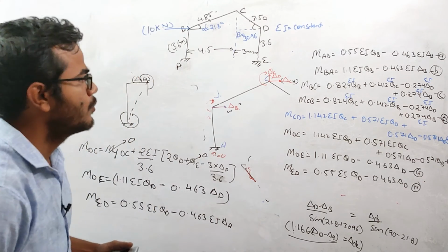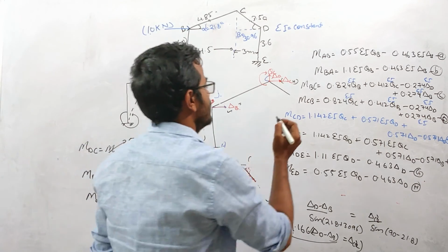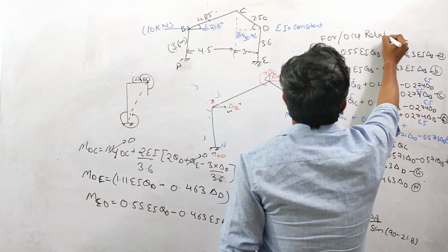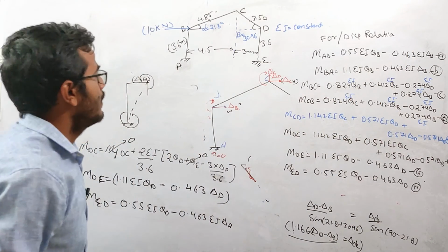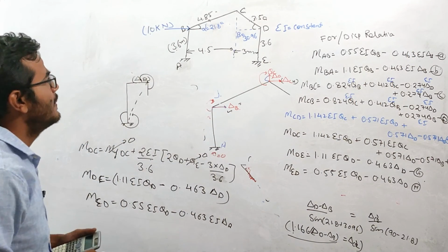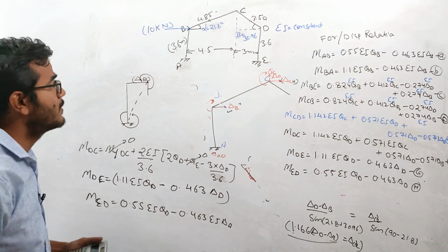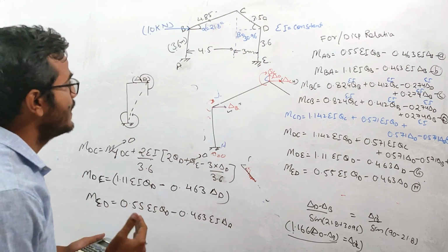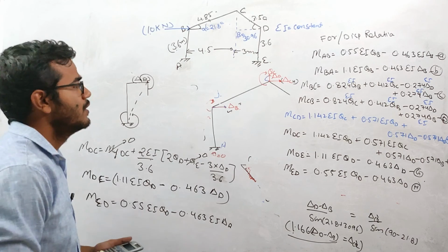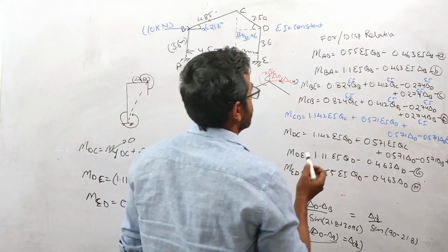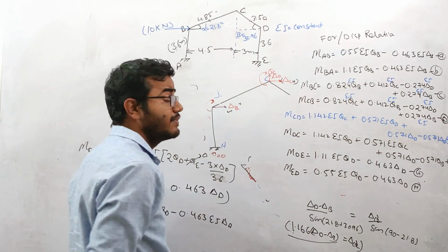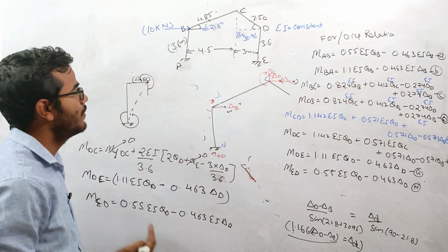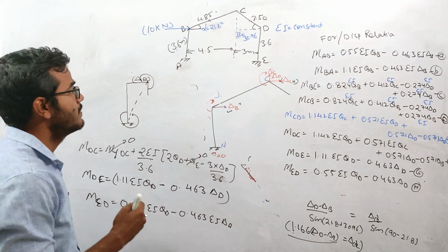Okay. So now you can see that we have established this force displacement relationship. After establishing the force displacement relationship, we will be using the concept of joint equilibrium, where we will be obtaining some equations corresponding to these displacements. So here we have 5 unknown displacements in total. So somehow we need to find 5 equations. Okay, so the next step is to form these joint equilibrium equations.